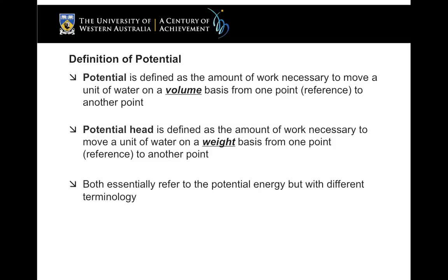So if you're a hydrogeologist, you might often talk about the groundwater head, which might vary from place to place. And if you stick a bore into the groundwater, and measure the height of the water inside that bore, that's the head that water has at that certain point, that certain amount of energy that it has.